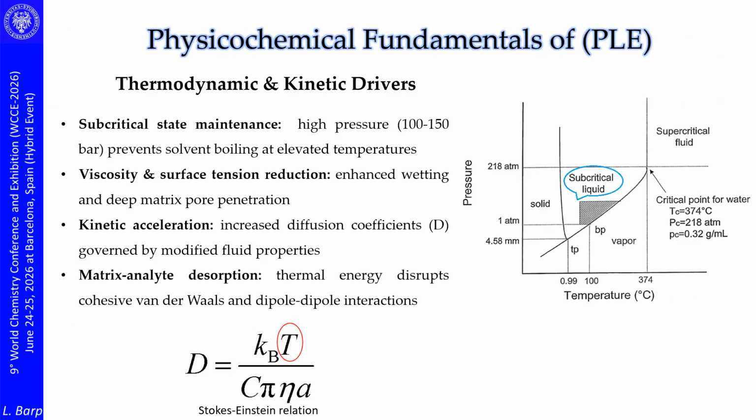To understand why PLE can be so effective, we must look at the thermodynamics of the system. By applying elevated pressures, generally restricted between 100 and 150 bar, we can maintain organic solvents or water in their fluid-liquid state at temperatures far exceeding their atmospheric boiling points.